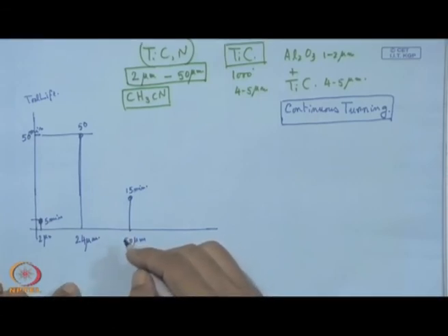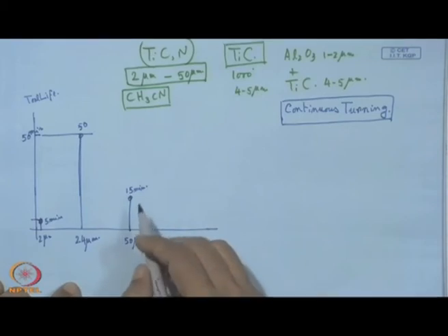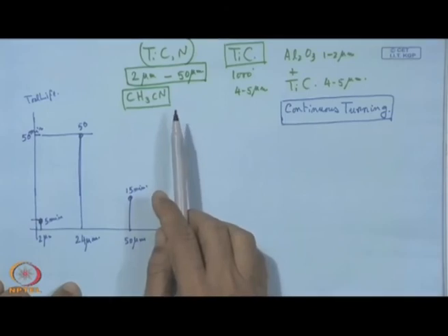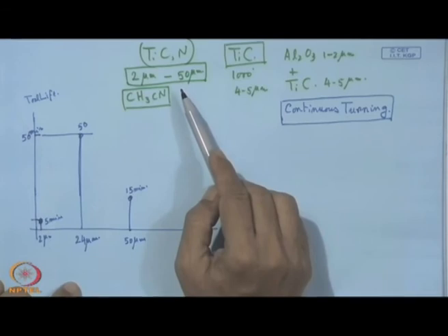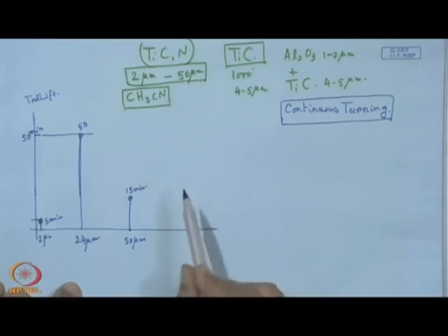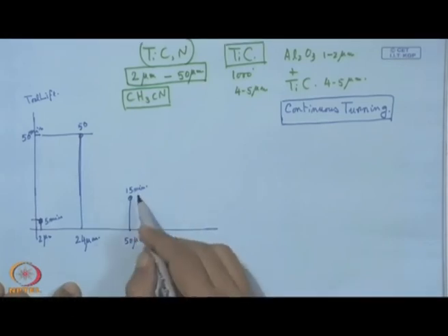It is not just gradual natural wear of the coating, but it is flaking, delamination and premature separation of the coating from the surface. That means, with the thickness of the coating, the stress at the coating substrate interface has gone up, and that was responsible for early separation of the coating from the substrate, and that leads to shorter life of the tool.